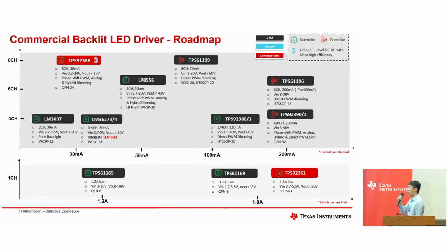So it's not 2 MOSFETs, low side and high side, integrated in it. It's a 4 MOSFET integrated solution that we hope will improve the boost efficiency up to 94 or 95%. It can benefit your applications on laptops or pads, extending the battery lifetime by about 15 or 20%.